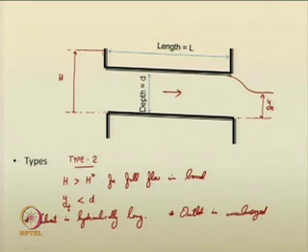So, you have headwater greater than the critical value. You have seen that H star is the critical value. For that, full flow is not ensured, that is a criterion. Then you have the tailwater that is less than the depth of the channel, then you have the bed, means flow is full here, culvert is hydraulically long.